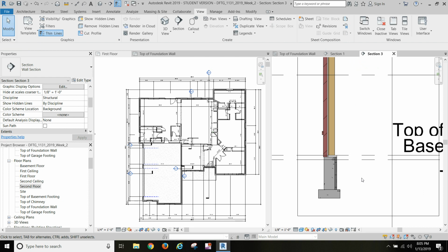Sheet A7. Wall section at kitchen, wall section at master bath, wall section at great room. These show what I would call a subsill. It's on top of the concrete and the insulation, and the top of the floor slab pours in flush with the top of that sill. And then your regular sill plate for the wall goes on top of that.